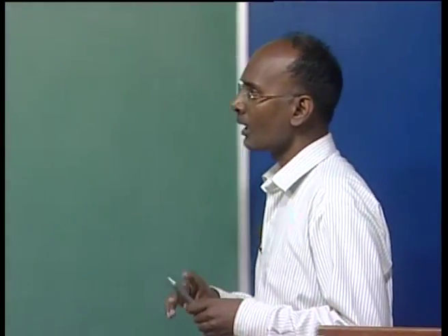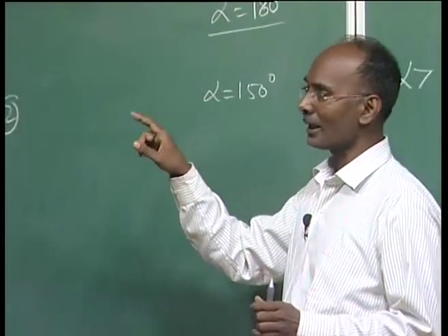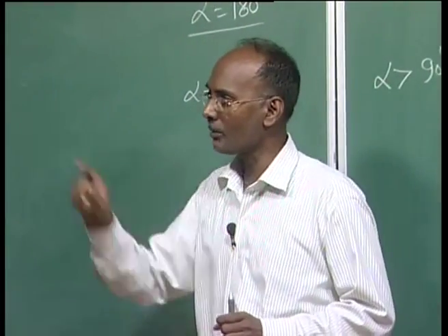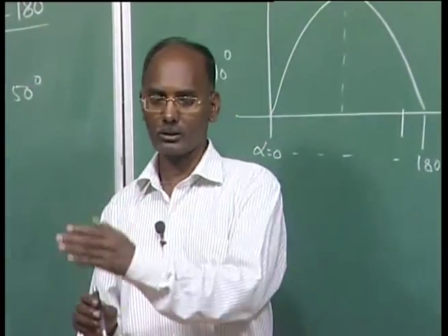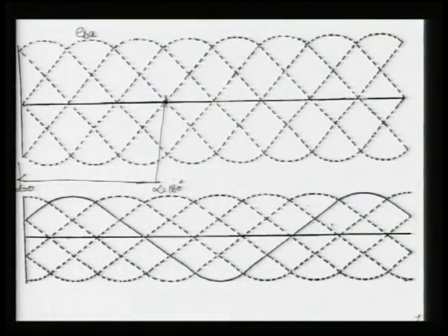Let us first draw it, and for knowing this output voltage we have to know the various line voltages. I have already marked EBA, then we have to mark the other line to line voltages very clearly. This is EBA, then displaced by 120 degree is ECB, and then another will be EAC. We have marked 3 voltages because you have to go for the cyclic one.